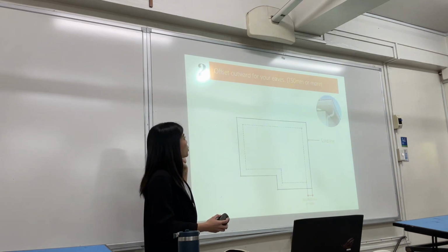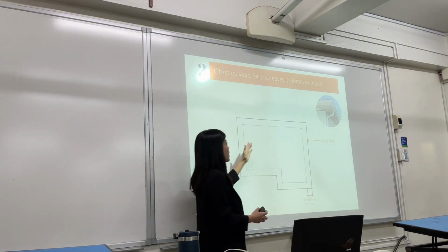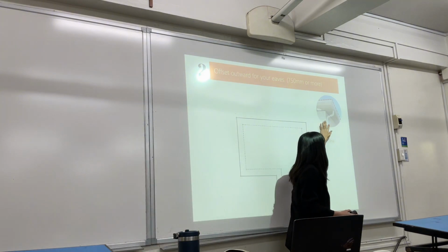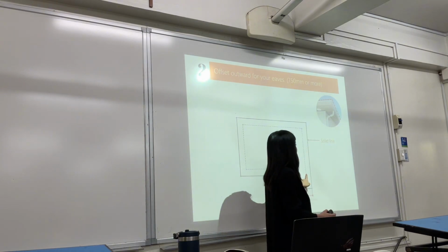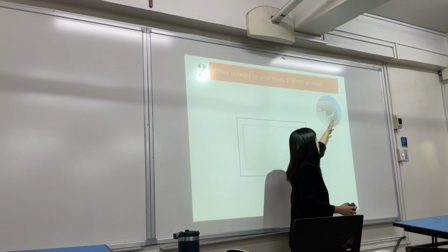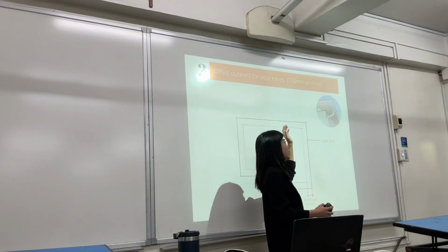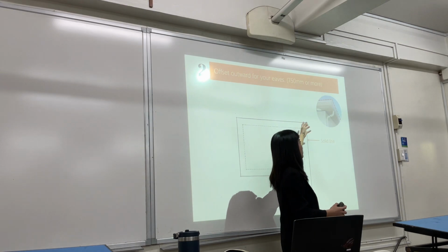Number 2. Your eaves. So, familiar na ba kayo sa eaves? Yan yung nag-extend from your exterior wall. So, ito yung kanina broken line natin. Again, i-guideline natin yan kasi yan yung offset natin for our eaves. So, yan yung extension, again, to divert the direct sunlight. So, it's very important na meron tayong eaves.